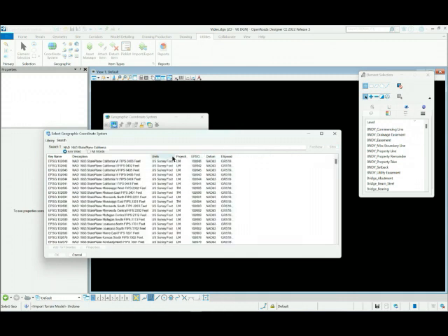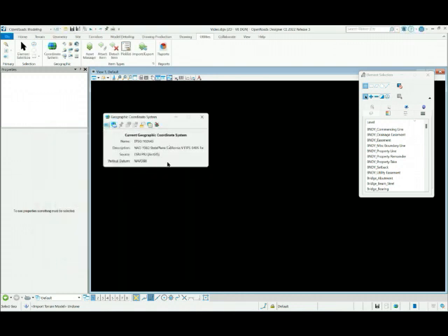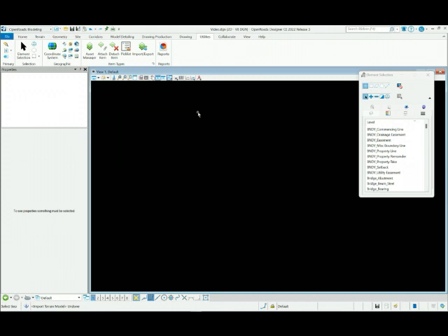The first thing you want to check is the units. Since my project file is under survey foot, all of these ones are correct. And then the project is located in San Bernardino, which is zone 5. So I'm going to click on this one right here, and I'll press OK. And now you'll see our coordinate system right here. Now I'll go ahead and close that.